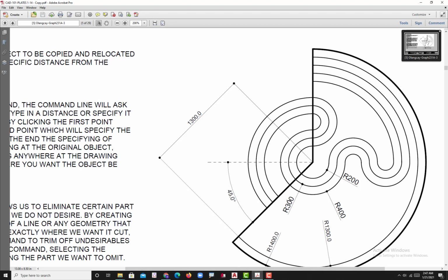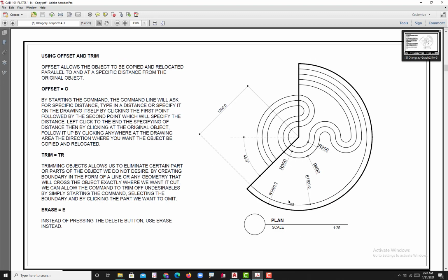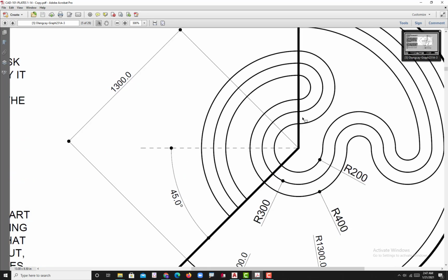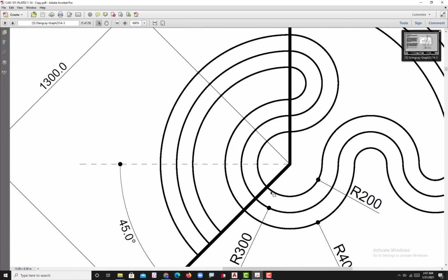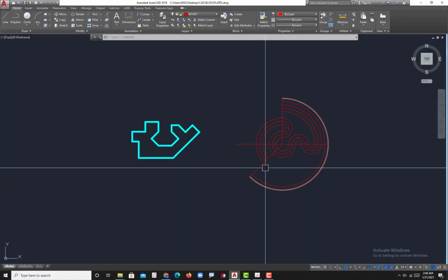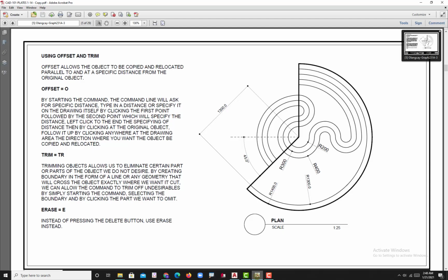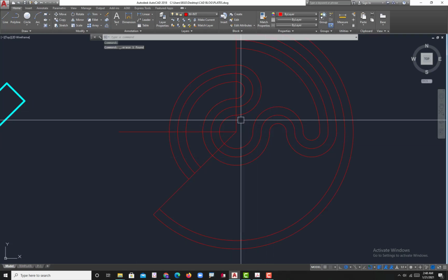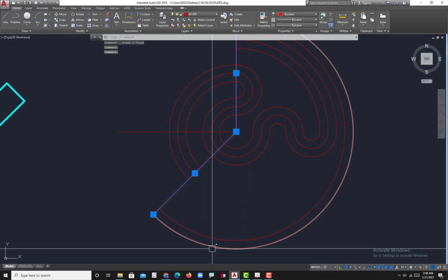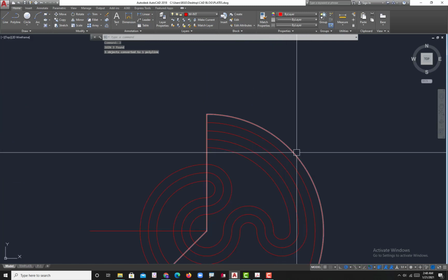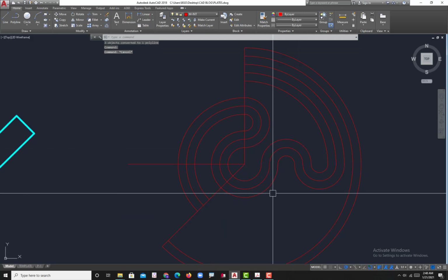Okay, so what you need to do is again, we need to beautify, no, basing it on this one, a thicker, a thinner line. And then there is a dashed line here, so we need to do that. Okay, so what we can do is remove this one. And then select this one, and then select this one, and then try to join them together. J for join. Do not group, no, so they are connected with one another.